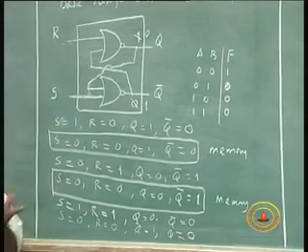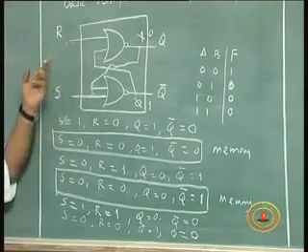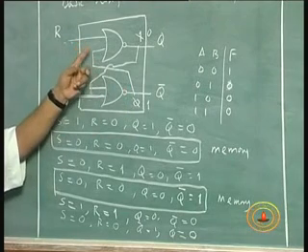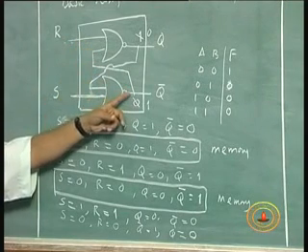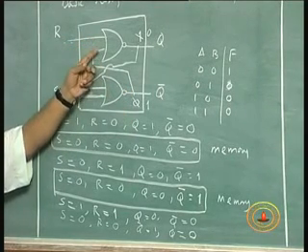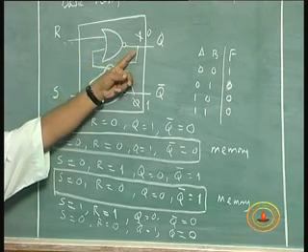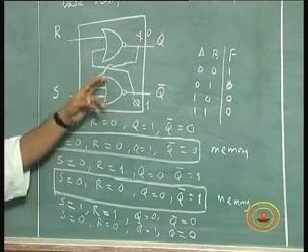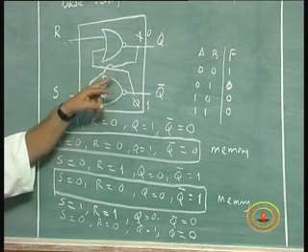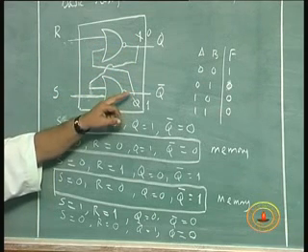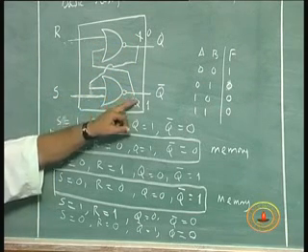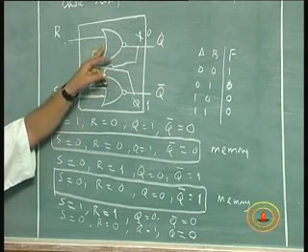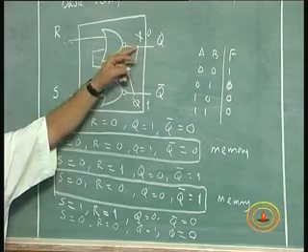On the other hand, if I started with this gate, this is 0, 0, earlier output is also 0, 0, so this is 0, this is 0, this is 1, 0, 0 will result in a 1 here, that 1 goes here, is a 1, 0, this is 0. So if I started analyzing this gate first, I get 1 here and 0 here. If I started my analysis with this gate first, I get a 1 here and 0 here.